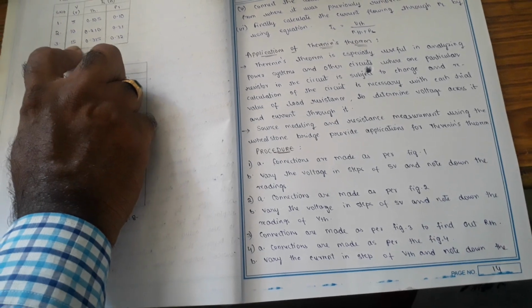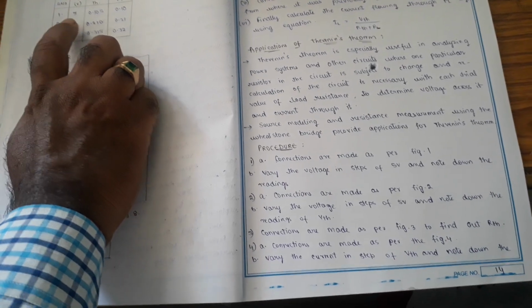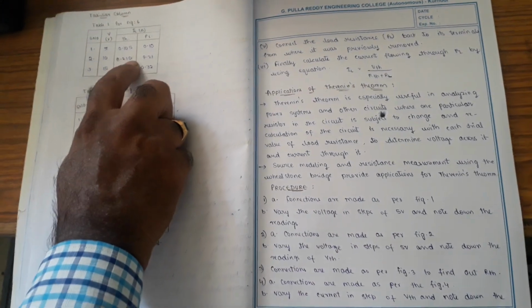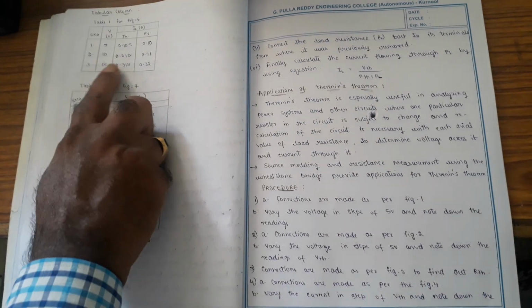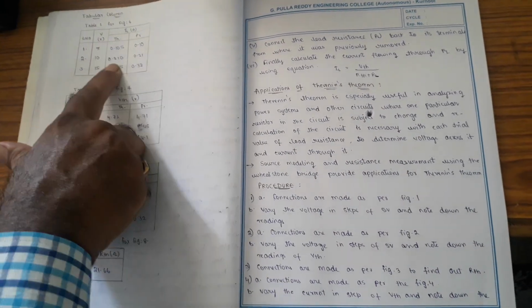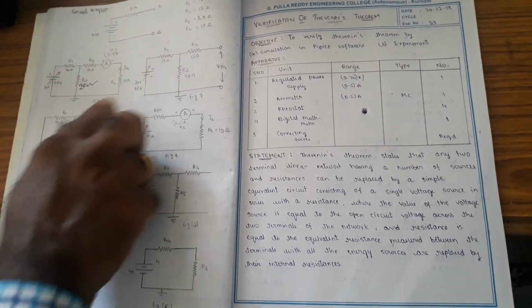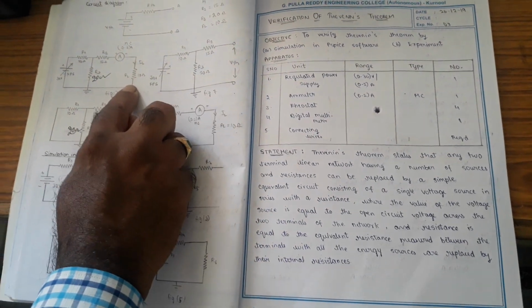The given values are 5, 10 and 15 volts. For 5 volts, the theoretical value is 0.105 for this circuit, for 10 volts it is 0.210 for the main circuit, and for 15 volts it is 0.315. Those are the theoretical values for the experiment on this diagram. These calculations may be done using either Kirchhoff's current law or Kirchhoff's voltage law. Our aim is to find the current flowing through the 10 ohm resistance.